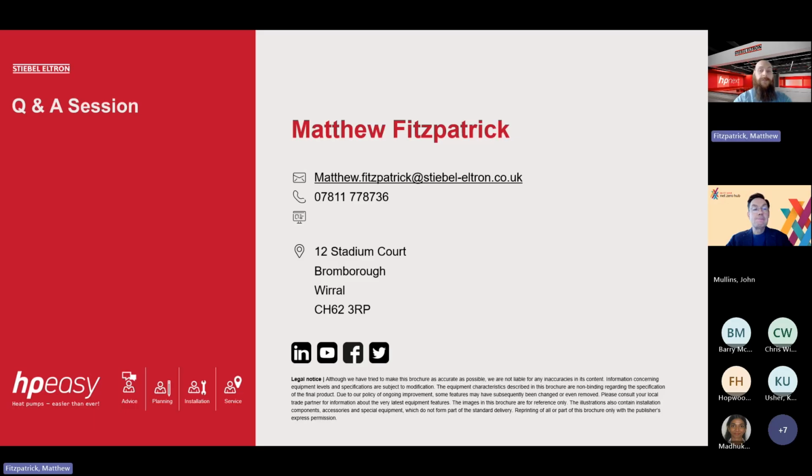On the other hand, if we can look to source modern cast iron radiators with a better heat output that will be suitable and brand new, then once we flush the system and new cast iron radiators are installed, we can connect directly onto that system. But the last thing we want to do is allow any debris to come through back into the heat pump and back into the heat exchangers, because they're connected to the refrigeration circuit.